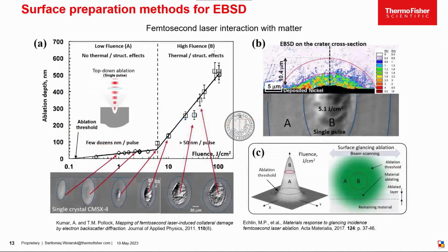This slide summarizes a series of experiments with various laser ablation energies and their effects on the damage in the superficial surface layer in a nickel-based single crystal superalloy. The key takeaways from the slide are: each material has characteristic parameters, namely the ablation threshold, that is the minimum fluence, defined as joules per centimeter squared, below which the laser is not ablating, removing material.